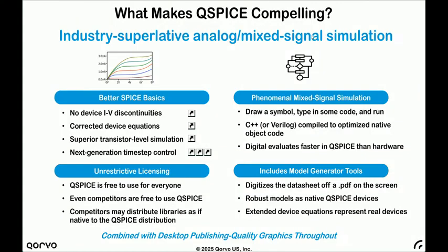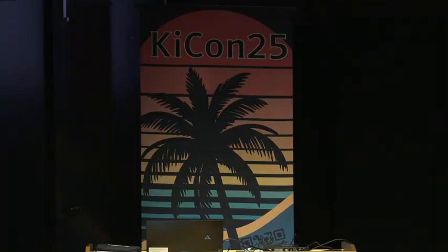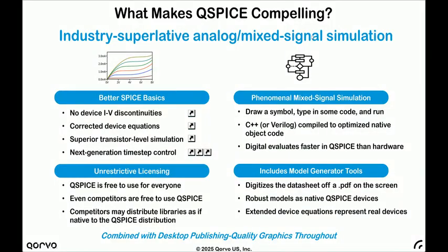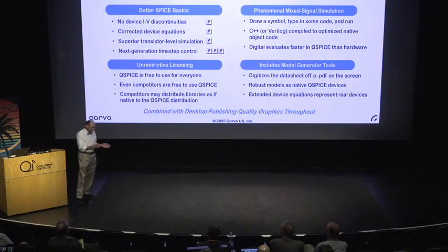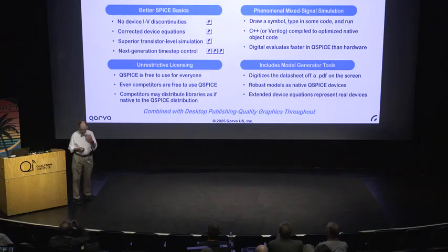This actually came because when I developed QSPICE, I was interacting with a number of IC manufacturers, and there are IC manufacturers that make power products that are wildly complicated for the amount of digital logic inside of them. I'm not just talking about I squared C to set the output voltage. I'm talking I squared C communication to set the commutation dead time, the number of pulses used to bring the switch node to pre-charge the boost capacitor. There are devices with 100 8-bit registers controlling, through divvying up the bit fields, maybe 100 different values, and you just can't do that in SPICE.